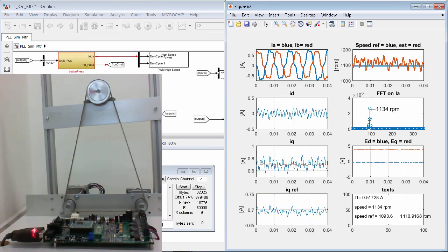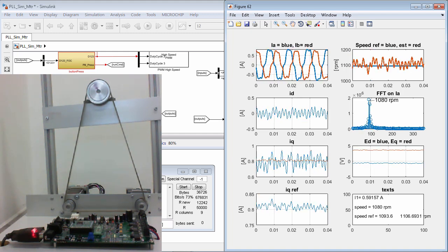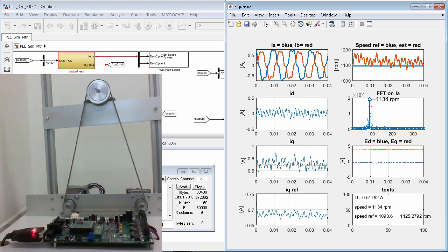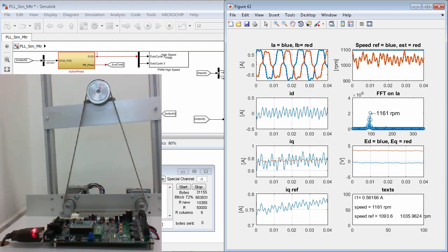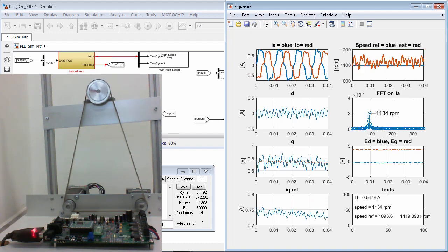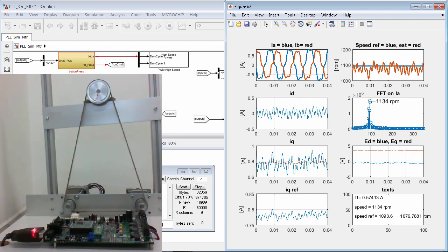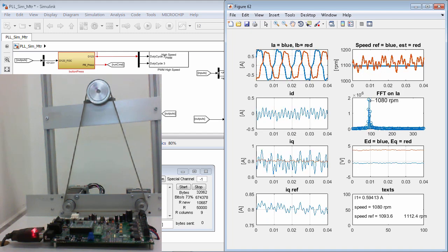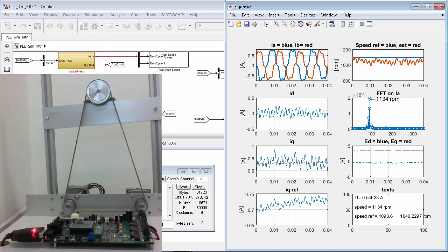Here you see the motor control evaluation board we will use during this webinar session. It is a motor control unit from Microchip targeted to control a brushless DC or permanent magnet synchronous motor. There's a sensorless motor control application running, based on a Simulink model. The control design was done in Simulink with the help of closed-loop simulations. Optimized code for the Microchip 16 and 32-bit MCUs was generated directly out of this model using Embedded Coder and the MPLAB 16-bit device blocks for Simulink.